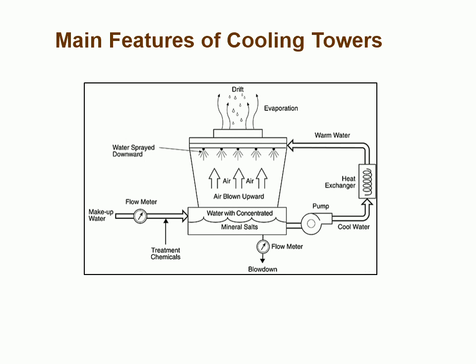This figure shows a cooling tower. Cooling towers make use of evaporation whereby some of the water is evaporated into a moving air stream and subsequently discharged into the atmosphere. As a result, the remainder of the water is cooled down significantly. Cooling towers are able to lower the water temperatures more than devices that use only air to reject heat, like the radiator in a car, and are therefore more cost-effective and energy efficient.